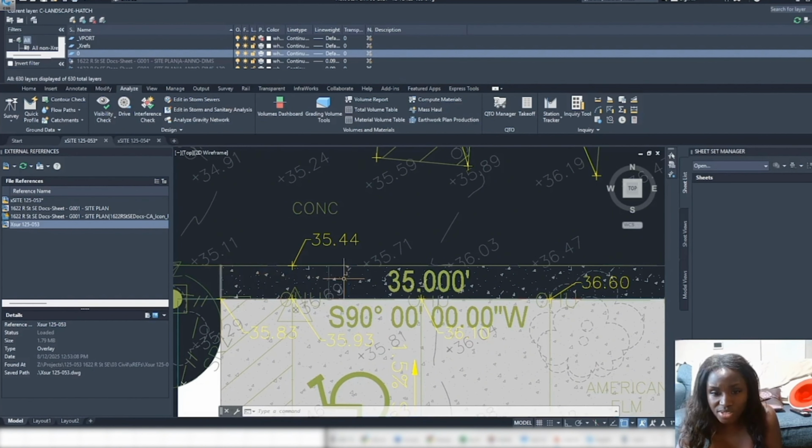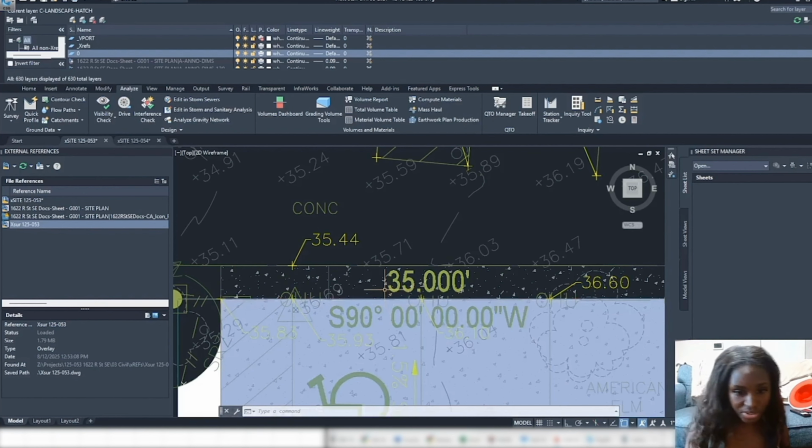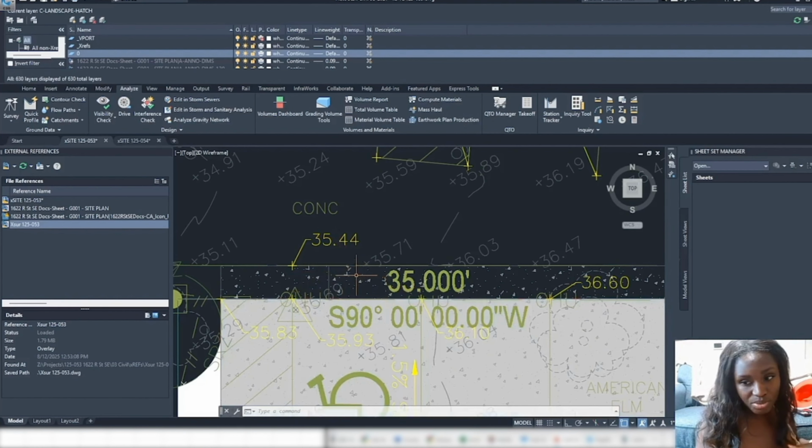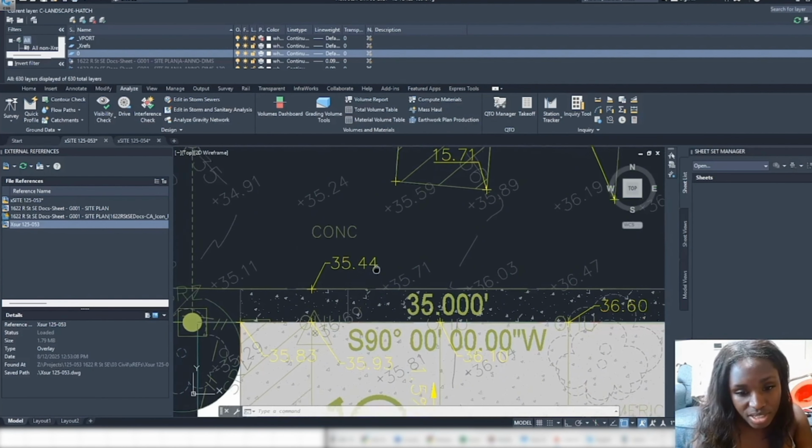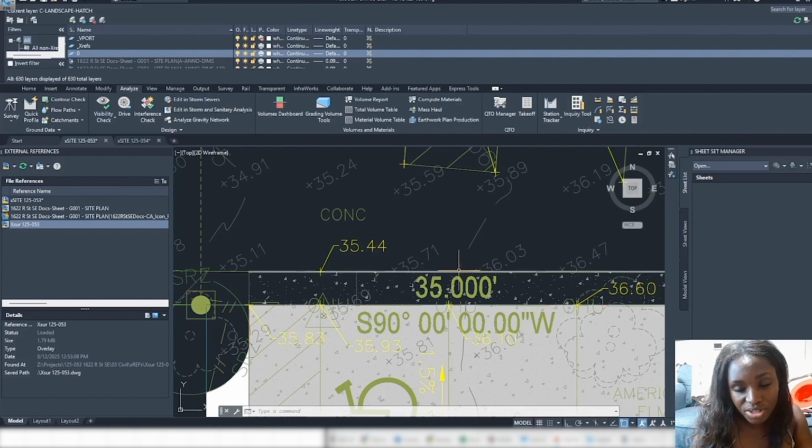We're going to do 12%, because that's a maximum for a driveway that is not covered. If this was a covered driveway, 20% is completely fine. You've seen parking garages all the time where it's about a 20%, 25% incline. I don't know if you've seen those covered parking garages where it's a 20% incline. But uncovered is max 12%. We're going to try to just do 12% here, increase. And then these two will be, let's see if they need that extra help. So let's go ahead and do that.